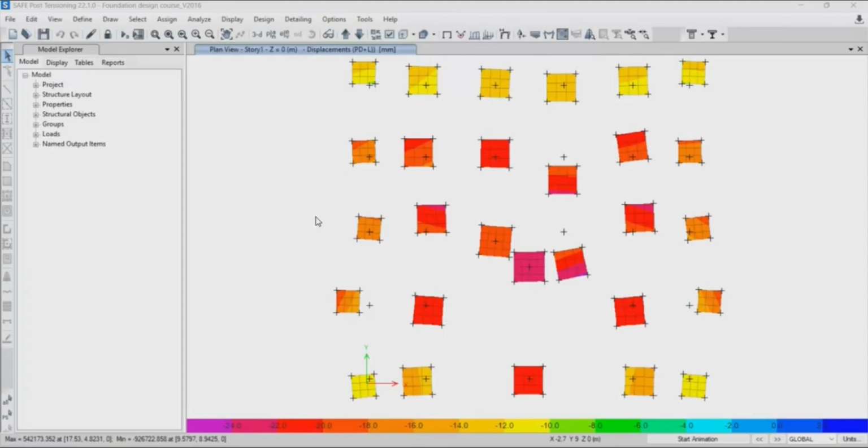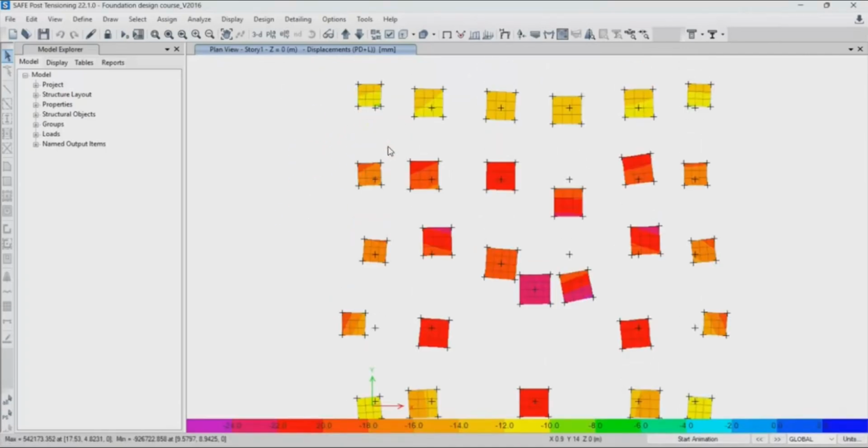Okay, so this check is very important. This is a critical concrete failure mode where the heavy column load is trying to punch a clean square hole straight down through your footing pad. That is why we say this is also called two-way shear. This check is going to tell you if your footing is actually thick enough to be able to resist the punching that is coming from the column.